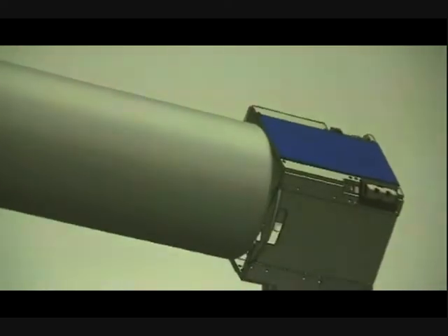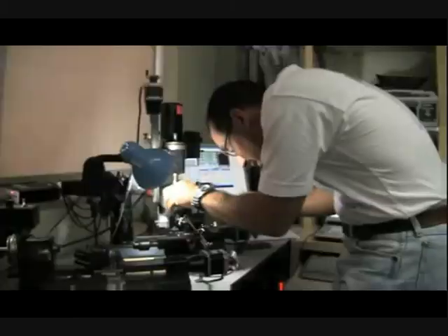These have particularly interesting performance in terms of attitude control, and we are able to achieve very fine angular pointing and very fine translation, relative position resolution. We talk about a few arcseconds of angular pointing and a few millimeters of linear resolution in the positioning. So in this way you can really have a very tight and precise formation flight of satellites working together to image a target on the ground and pointing on this target while they are flying on top of it with very high precision.